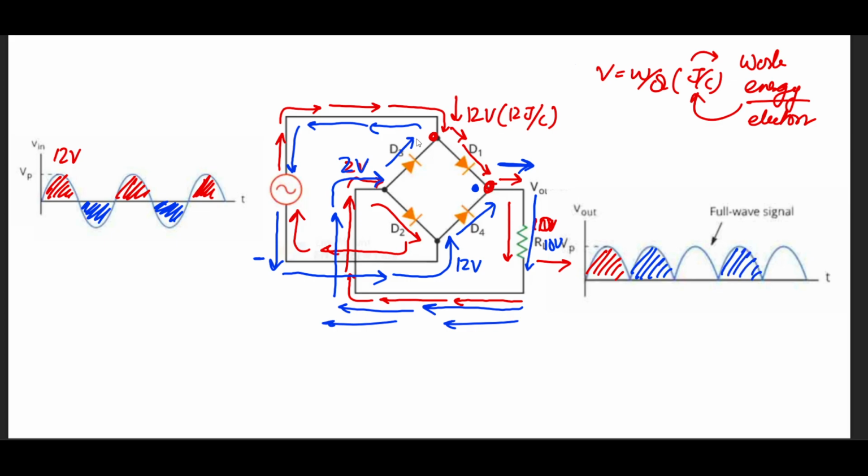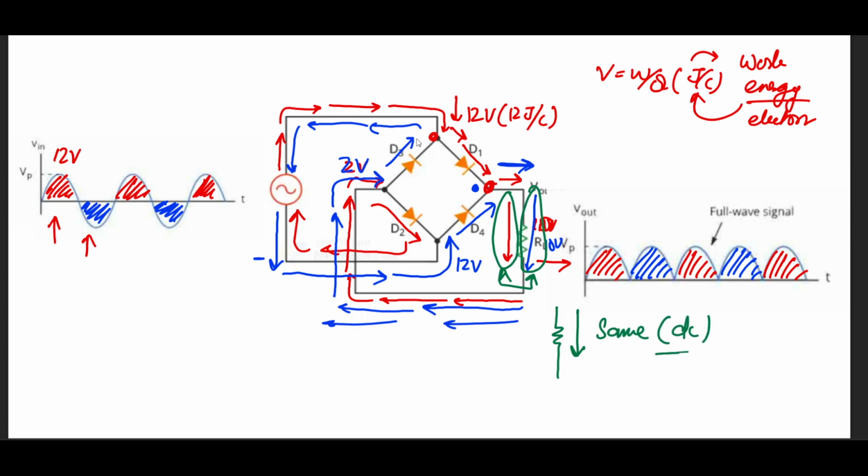So this is full wave rectification. What we've done successfully is extracted both phases of the AC electricity as the output. Right now they are pulsing between a positive maximum value and then 0, then positive, then 0. We notice this, but we acknowledge that no matter if it is pulsating or constant from a battery source, the current always remains in the same direction. In the resistor it is always moving downwards in this situation.